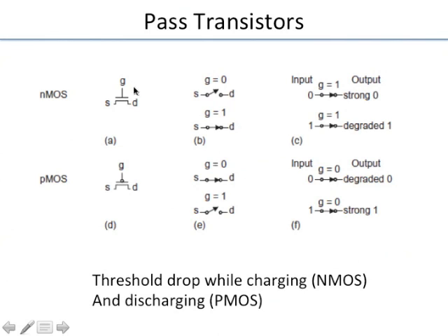So what is the current drive given by? It is given by the potential between G and the source. To begin with, source is 0, gate is high, so you have a very good gate overdrive. Gate to source voltage is VDD, threshold voltage is VT. So VDD minus VT is the overdrive, and you will get a good current. You will have an onrush of current. But as this node starts going up, you see that this gate overdrive starts dropping. It's like a self-limiting effect.